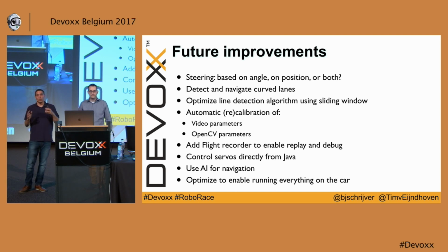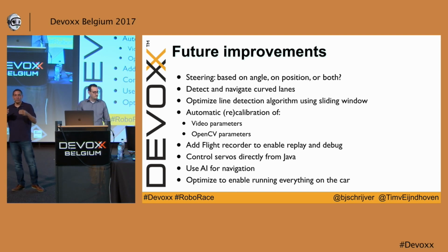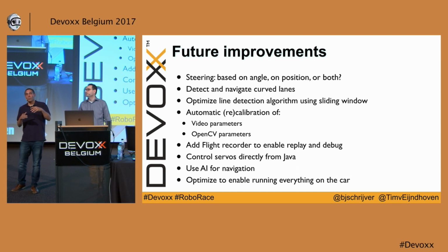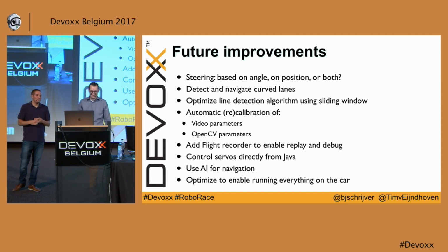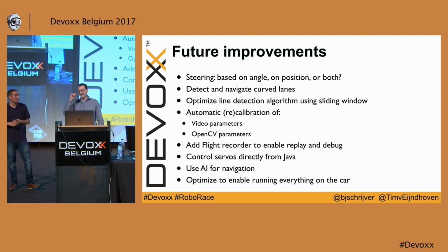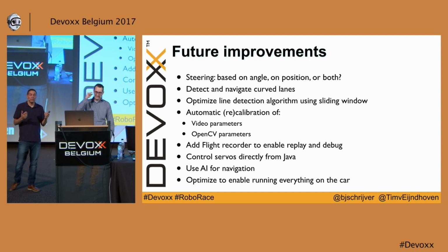We're currently controlling the servos by just making a Java system command doing echo 0=150 to /dev/servoblaster, which isn't really nice. It's pragmatic, I would argue. It works. Yeah, it's fast enough also.